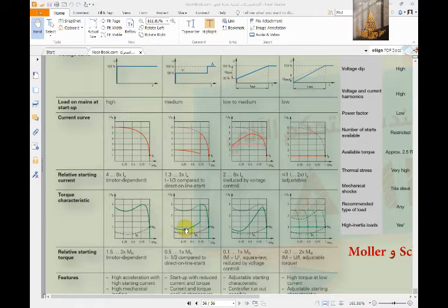But according to star delta, we will find the torque very weak, very weak. It maybe reaches more than the minimum torque, just a little bit. Then when you're reaching that star, still weak, then at this point it changes to connect the delta. It's taking the torque full curve like this path. It takes the torque curve correctly.